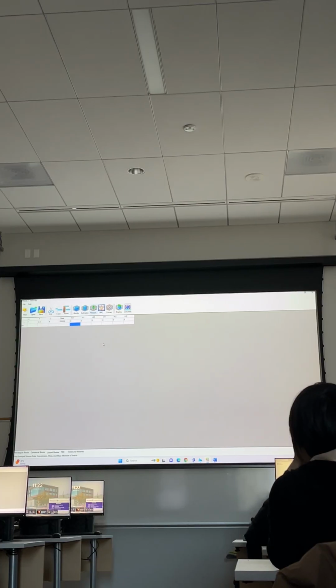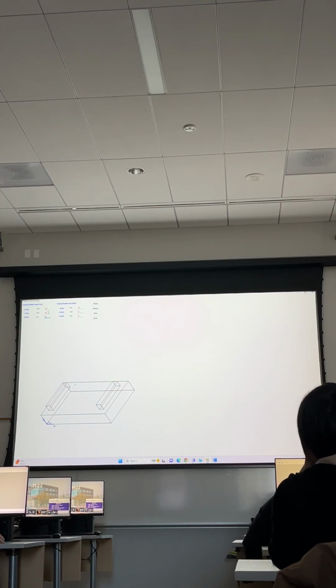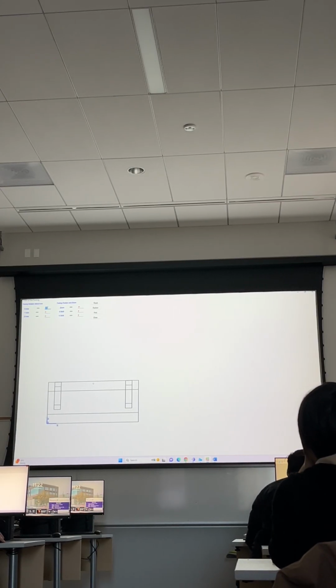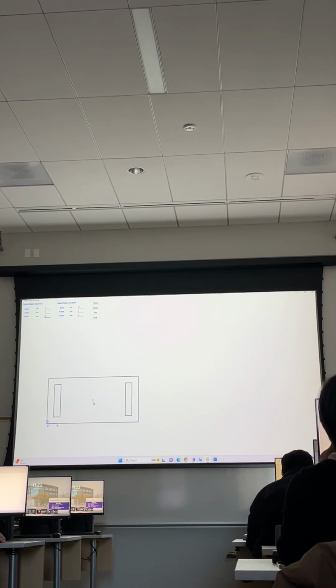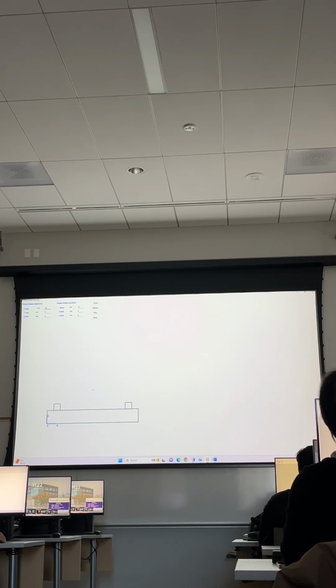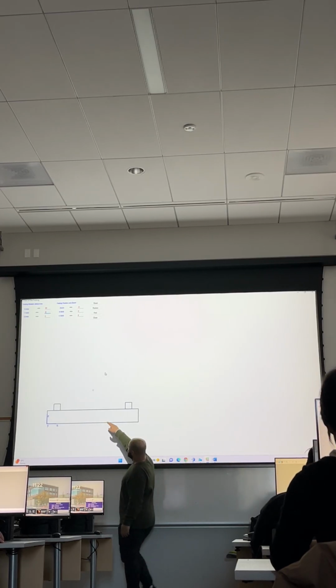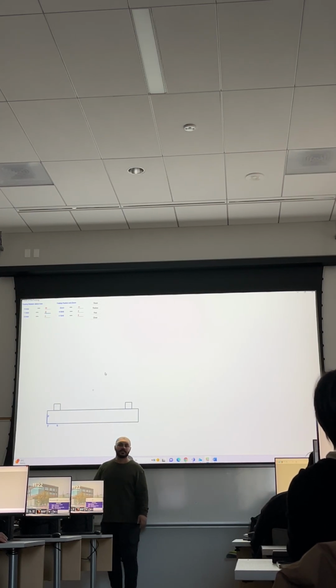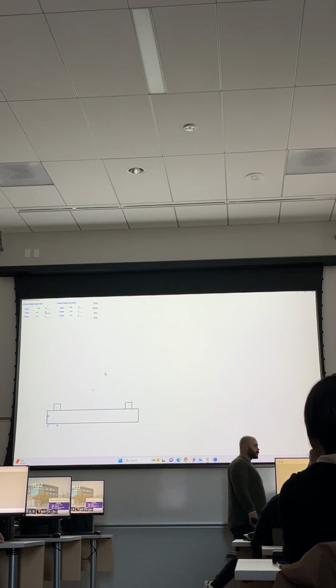Okay? Again, after you're done with this step, you can display it. You will find here this point, this small circle in the center here. This is the mass we just defined. Okay? So if we put it like 90 here, in the elevation, you will find it 3 meters above the foundation. Okay? This is the mass we just defined. Is that clear?